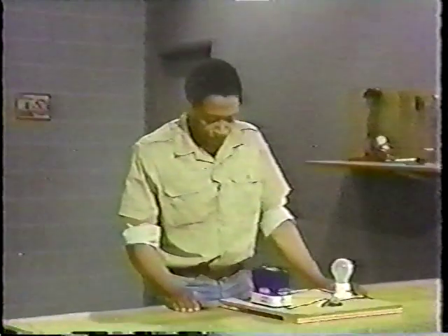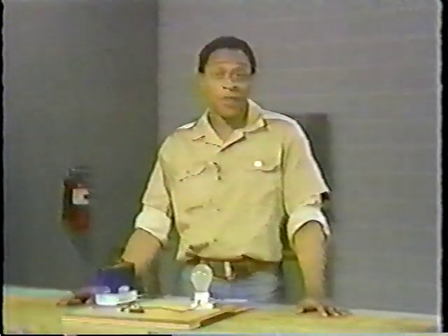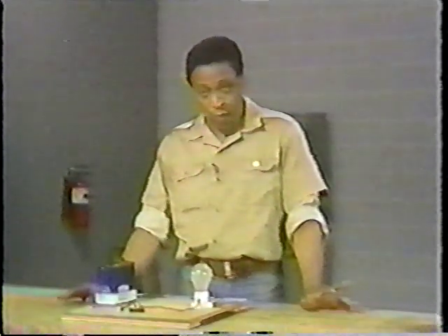When you're doing a repair, you'll find you use Ohm's law without even realizing it. For instance, if the resistance is extremely low, you'll know that the circuit is shorted, and you'll take steps to find out why. Well, that takes care of current, voltage, and resistance. But there are a couple of other things we need to mention before we're through. Power and energy, and the units they're measured in, watts and watt-hours.